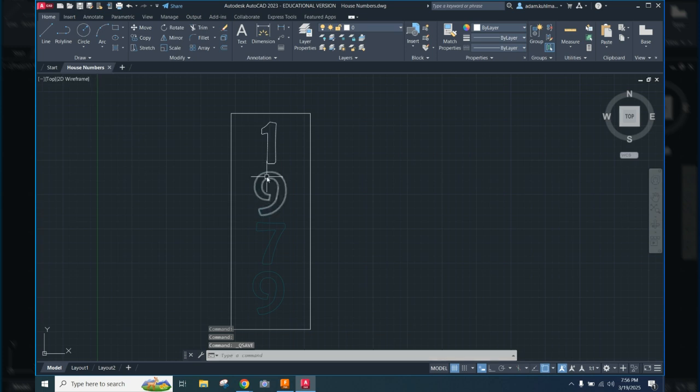All right, now we're going to set up our layers. When we cut this thing on the plasma cutter, we need to have continuity for the electrode to run through. Okay, so what that means is we got to start at the center and work our way out. If we were to cut this rectangle first, it would free our piece of metal from that big piece of metal, and we may not have electron flow through the whole thing. So we always want to start at the inside and work our way out when we're doing this.